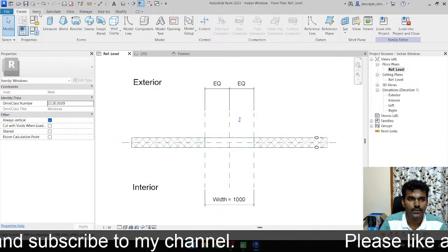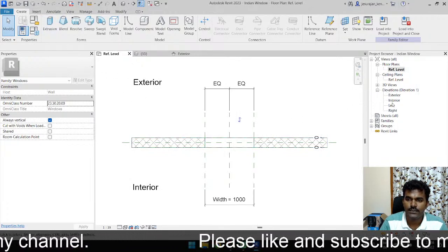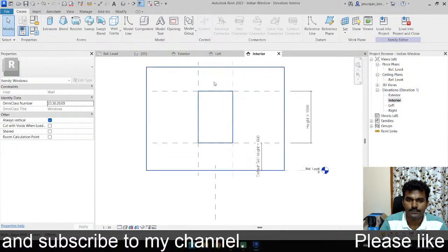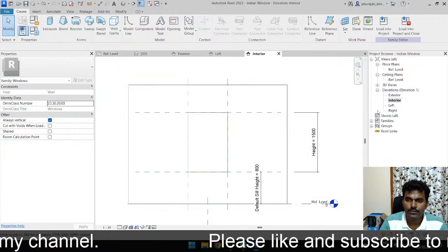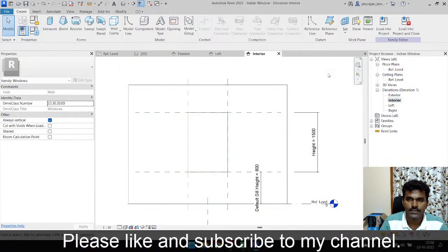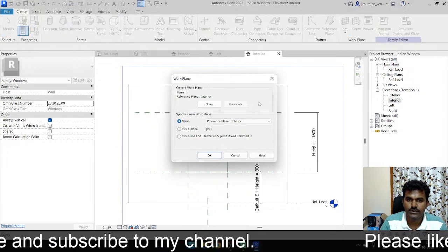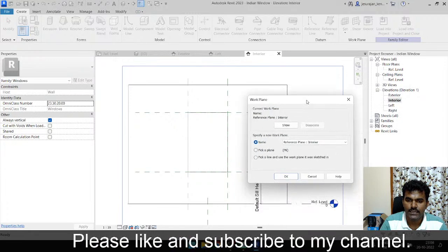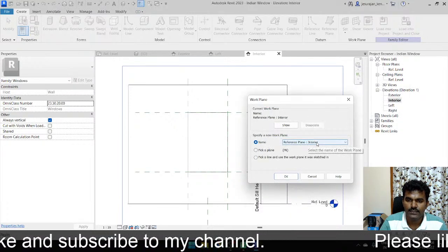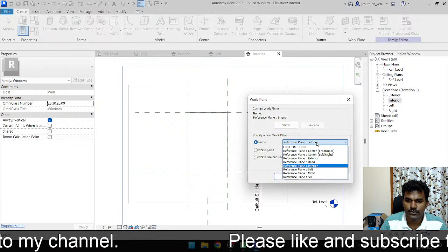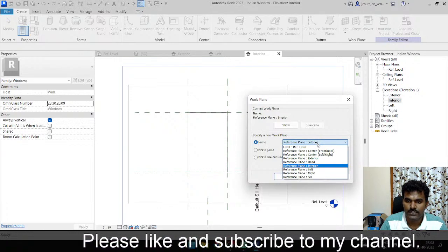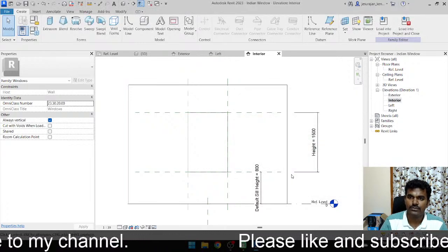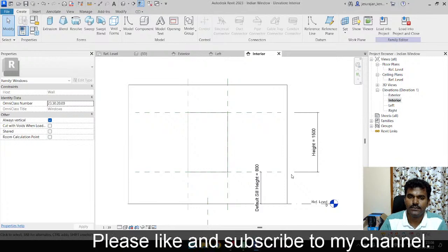Okay, so everything looks fine. Go to exterior, interior side. So this is my interior side. First I have to check which work plane is available, which work plane I'm going to draw on. I am on the interior side and the reference plane is interior, so I'm just going to change that to center, front or back. So you have to check your work plane.